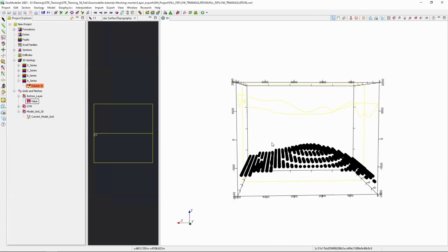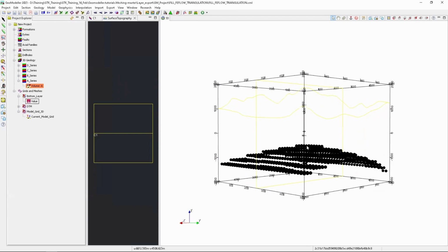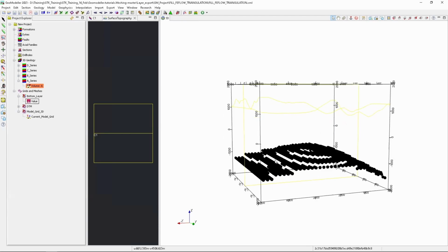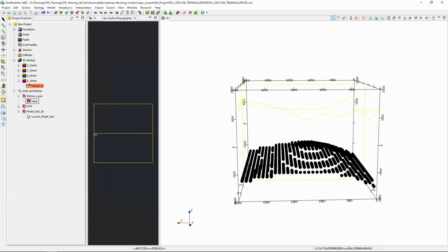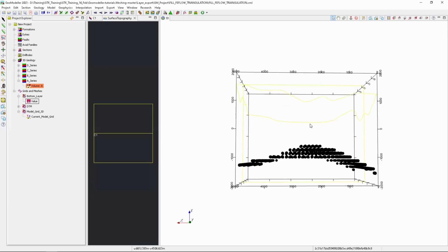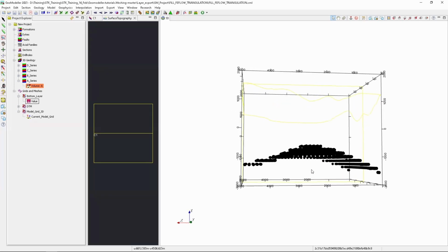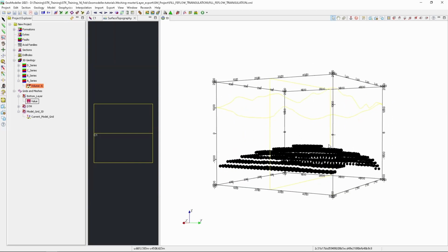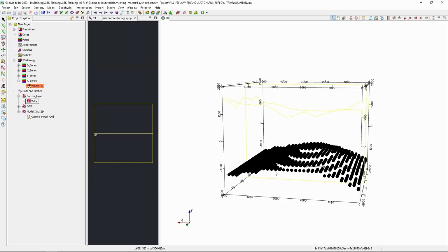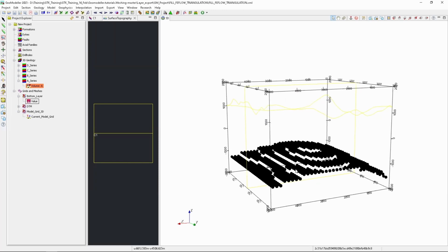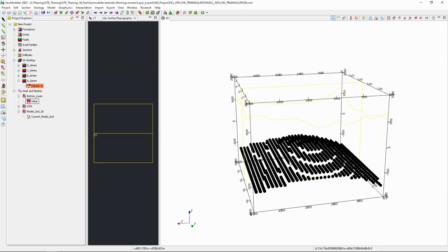So this CSV file can be used anywhere to create the layered mesh, either in vFlow or mudflow environment, for creating the same geological layer. One thing to note is that this provides us accurately created surfaces based on implicit geological modeling and the data available to you. And after that, exporting information from here will lead you to create an accurate finite element meshing for your mathematical simulations.